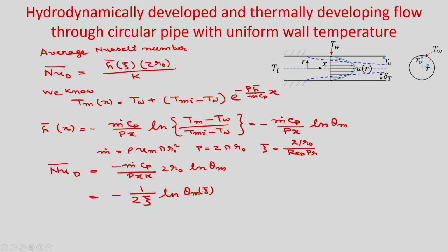Okay. So, this is the average Nusselt number. Now you can see, to find the local Nusselt number, average Nusselt number and the temperature distribution, you need to find the eigenvalues, eigenfunction and those constants Cn and Gn. Once you find those numerically, then you will be able to find the temperature distribution and the Nusselt numbers.